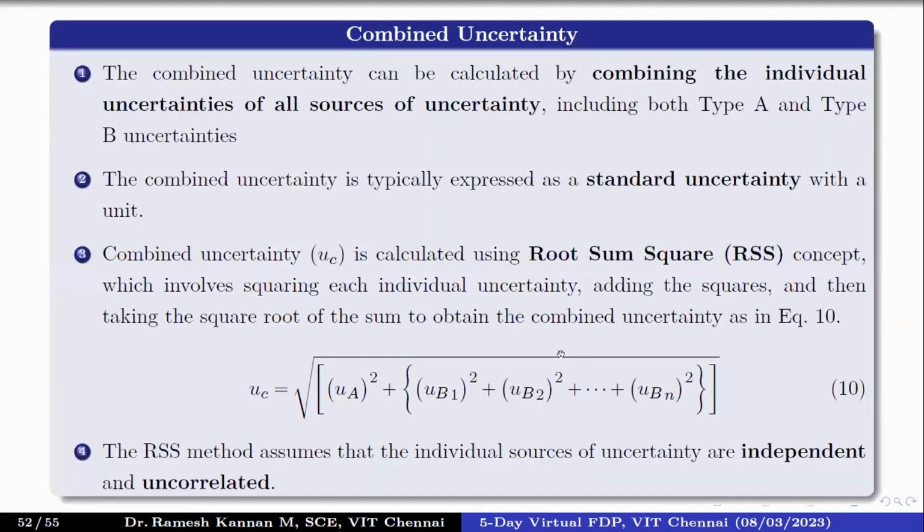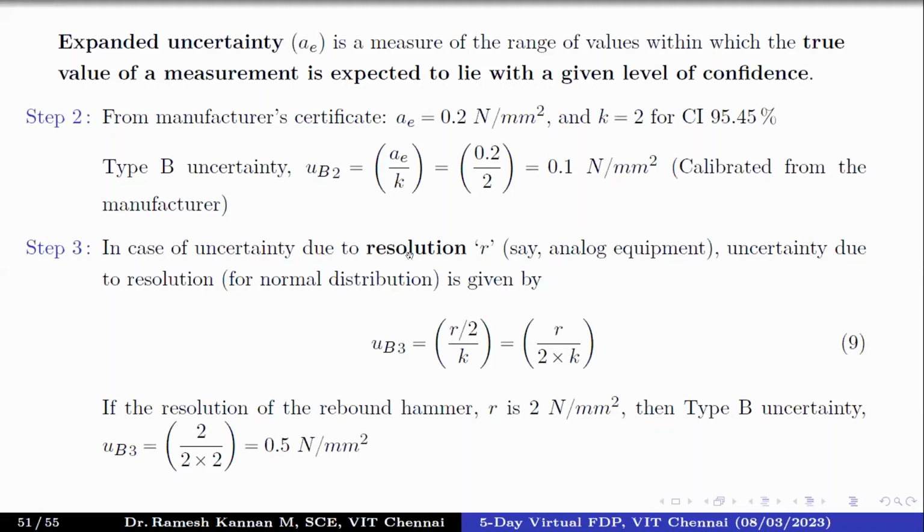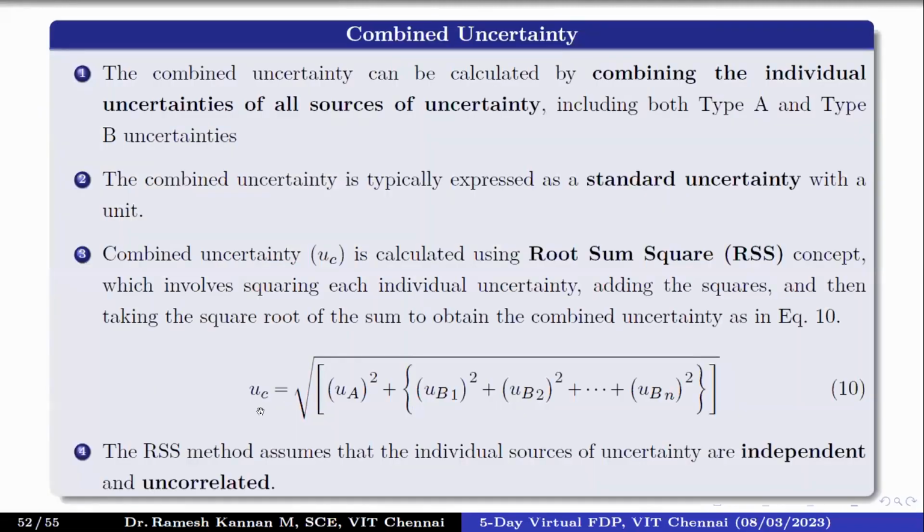We have to give independent uncertainty, say for example, resolution, or in terms of temperature, humidity, whatever factor might cause uncertainty. All of those you can add, and that will give us the combined uncertainty. Combined uncertainty is actually the standard uncertainty. Even an NABL laboratory probably finds this out in a bigger Excel table of columns, where type A and type B are put together, and they consider this the true or final uncertainty.